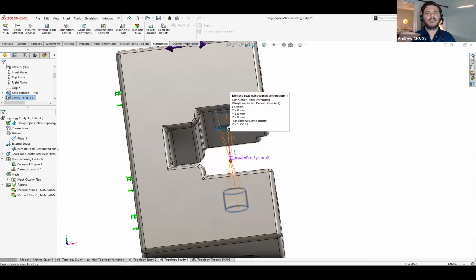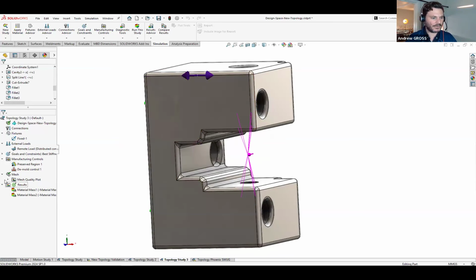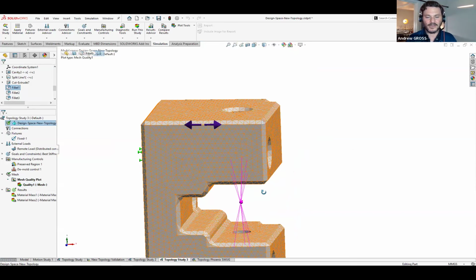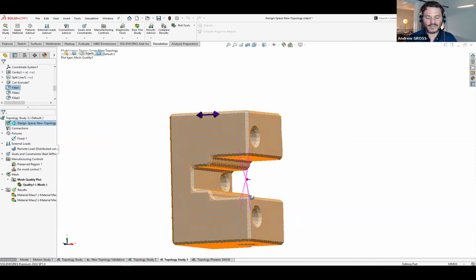And then, in a serial process, it's deleting solid elements from the environment, saying this is not needed. It starts from the easiest stuff, which would be elements out here. I'll show you the mesh so you can see it. So it'll start with elements at the furthest distance. Like this element is probably one of the first elements deleted from the design space. It's saying, don't need that. And then it just keeps deleting them until it says, oh no, I now see